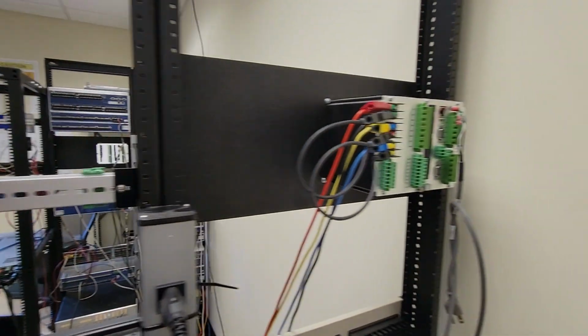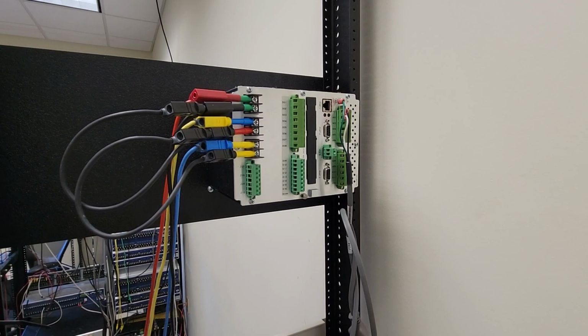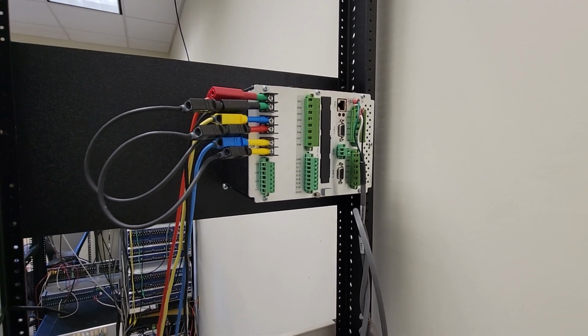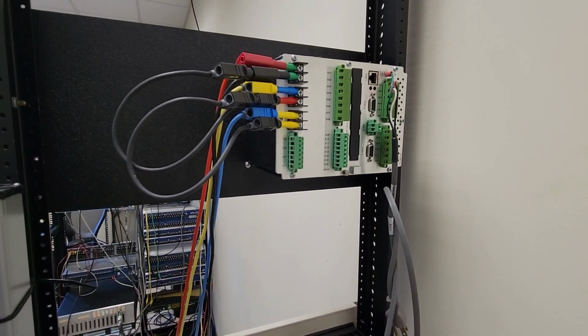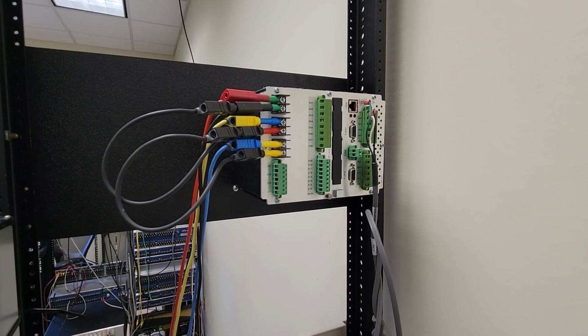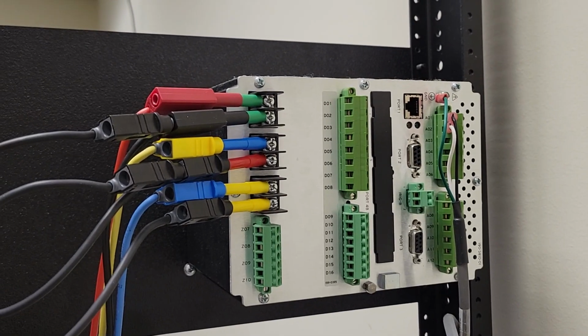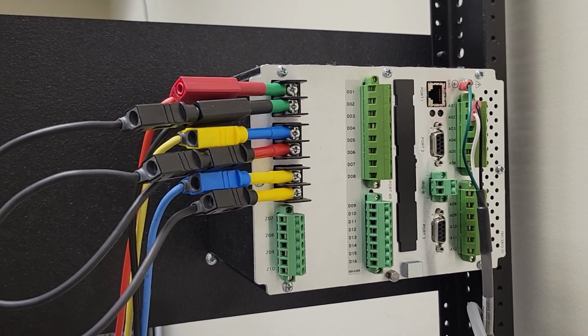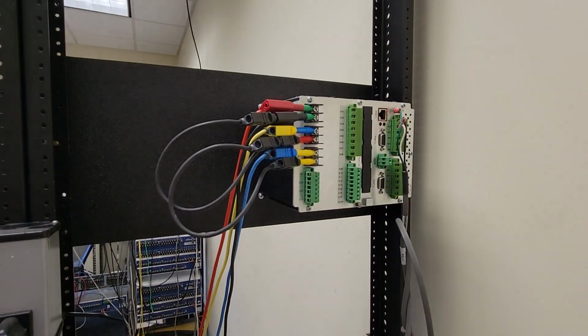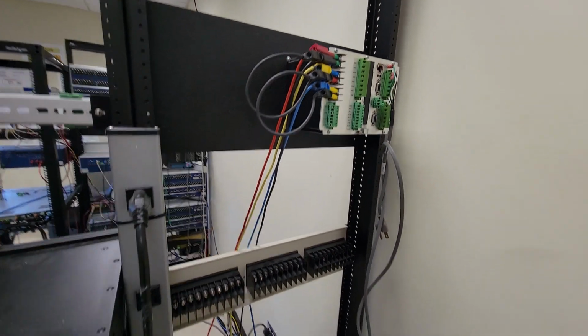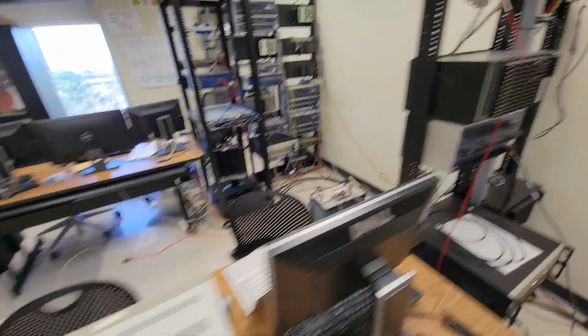And then you have this Schweitzer 735 revenue meter that really is just acting as a terminal for the circuit to be observed for injected currents. And you can see it's got the A phase, B phase, and C phase, as well as those Y connected, those connected neutrals that go back to the power system simulator.